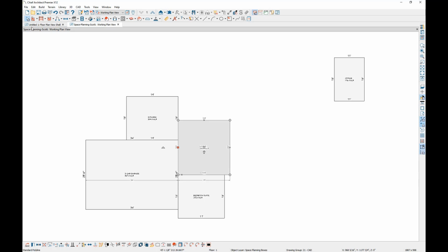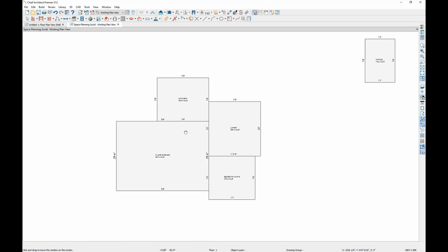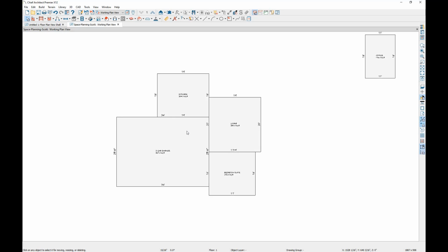And then the process that you would end up using to turn this 2D visualization into your 3D house is start tracing these CAD lines with your wall tool. So that's pretty convenient because your walls will snap to CAD. If I use my wall tool and I just hover over the corner, you'll see that red handle that's telling me it's snapping, and then you can just click and drag and it's going to snap the main layer of that wall assembly to the edge of this line.